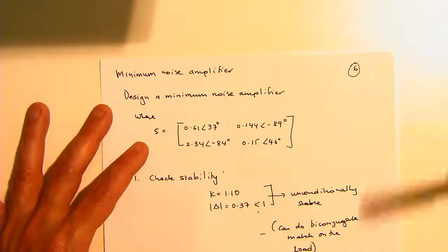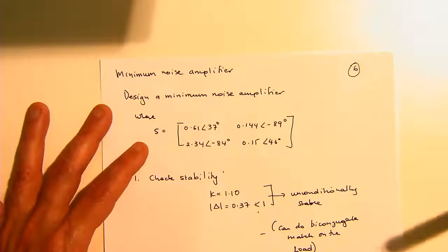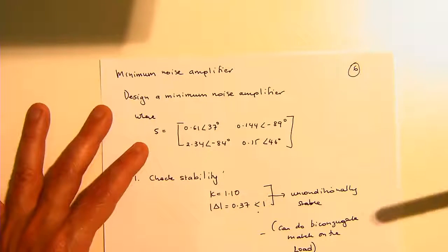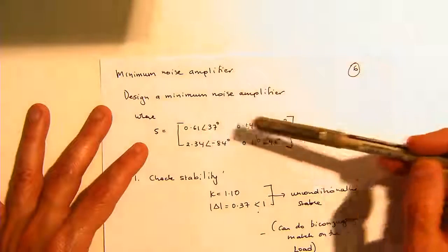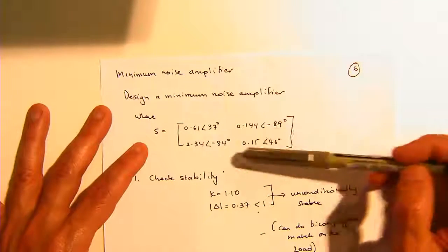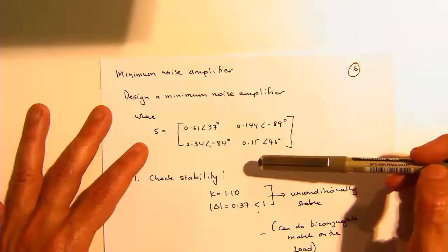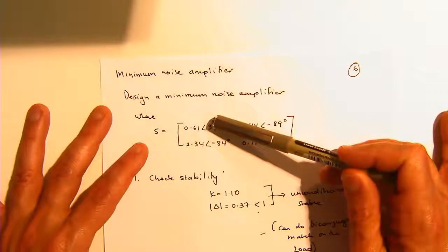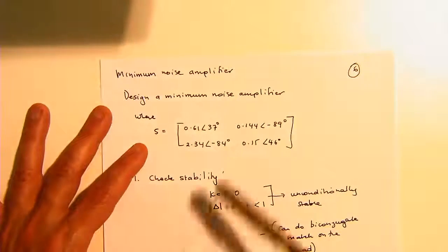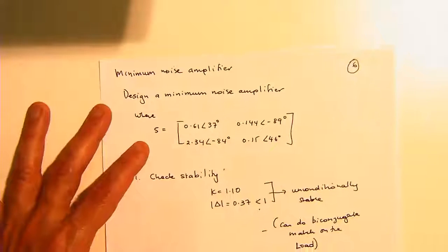When you're looking at data sheets, that's a standard of how people present the scattering parameters. Now, okay, question. What are all these values? Just making sure that nobody's forgotten. What's this one? All right, perfect. Okay, S11, S12, S21, S22, perfect.